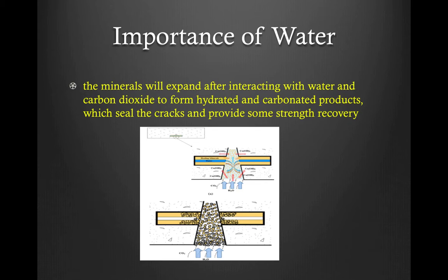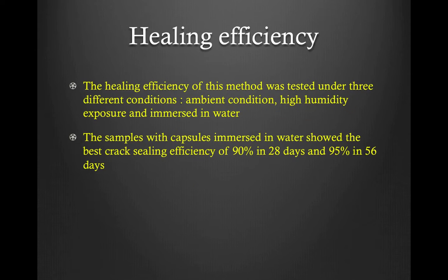After the glass capsule is broken in the figure, minerals will expand after interacting with water and carbon dioxide to form hydrated and carbonated products, which seal the cracks and provide some strength recovery. The healing efficiency of this method was tested under three different conditions: ambient condition, high humidity exposure, and immersed in water.